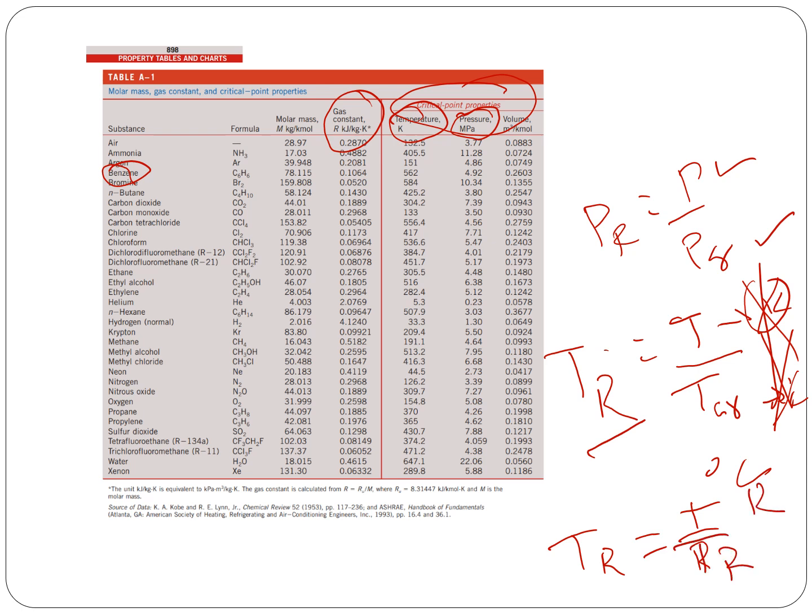Very important. Whenever you are using the ideal gas equation, or the ideal gas equation with the compressibility chart, make sure temperatures are always in the absolute temperature scale. Don't have the temperature in either Celsius or Fahrenheit. You won't get the right answer. It's a very important thing to consider when you are solving problems using the ideal gas equation or the ideal gas equation with the compressibility chart.